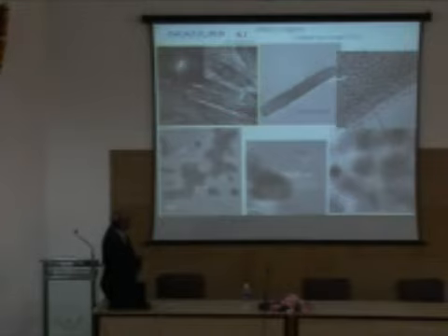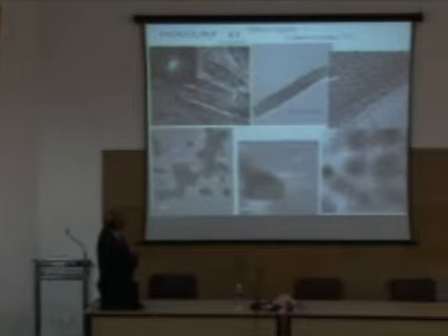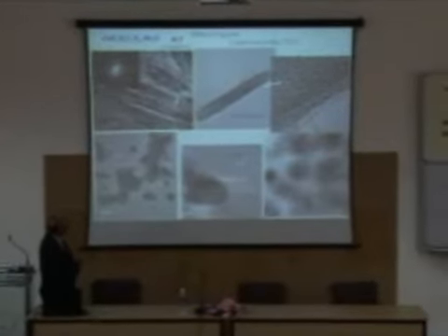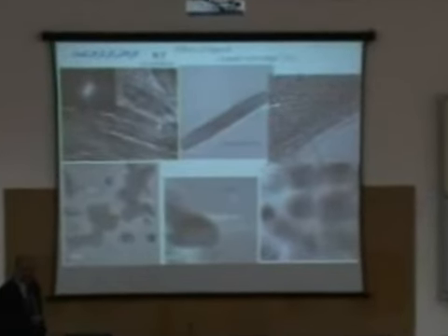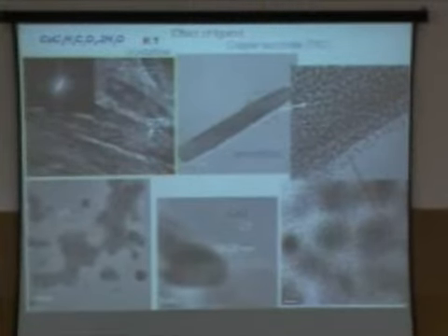So in the high resolution transmission electron microscope, you can see these very ordered structures, and this is called the fast Fourier transform or the electron diffraction. This is in the reciprocal space, this is the real image, and that shows these fine spots, and that is an indication of a very highly crystalline nano rod. Now we can change this highly crystalline rod to an amorphous rod.